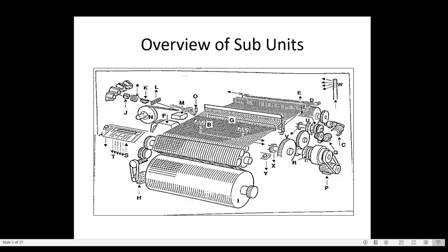Then we can see here left hand flywheel is there, the drive goes to the left hand flywheel. Here also right hand flywheel will be there, the main shaft drive will be going to the right hand. Here only the left hand flywheel we can see. So Rapier drive is there, from main shaft the drive goes to the Rapier drive. So in the left side we can see 3 drives have gone. One is the Dobby or Jacquard, then left Rapier drive, then weft selector device.